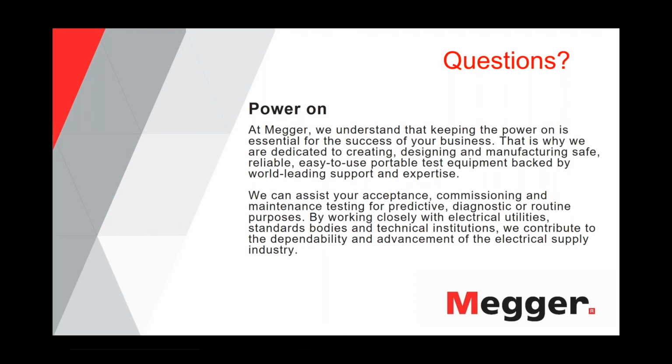When you run it again and you didn't change the configuration, maybe in 2 years, and you look at the leakage current, if the leakage current has increased, then obviously it's going not to the better. And companies record these leakage currents so they can see the trend of the insulation.